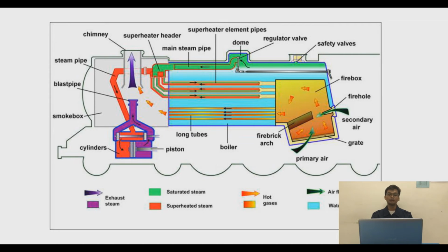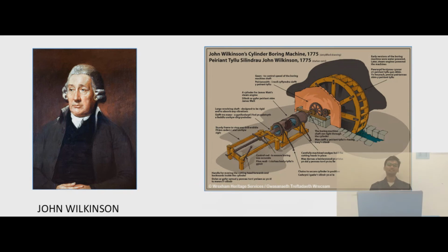Many of them are unavoidable, but we can improve the situation by upgrading the piston cylinder. The manufacturing techniques needed to bore accurate and strong piston cylinders were not available in the early days of steam engines. That changed when John Wilkinson invented the boring machine, which allowed for precise machining of solid iron cylinders, which reduced steam leakage and made the piston cylinder stronger, thus allowing max pressure to rise.